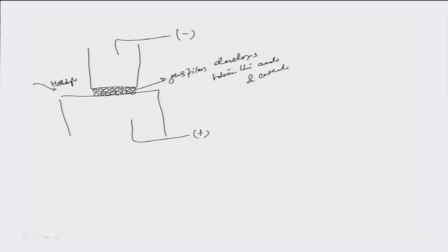So, this leads to the formation of an insulating gas layer, I would say, and again the concept of discharge may come in here, as was illustrated in case of EDM before. So, there is a discharge which happens because of the electrical breakdown of the gas like medium, and the film actually gives way to a path for the electrons to flow between the cathode and the anode, and it is by thermal ablation that eventually the bulk material is removed.